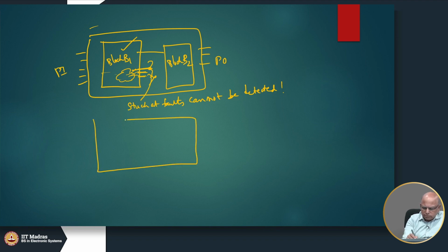Another thing could happen, right. I may have block B1, block B2, I connect all these guys, and there may be some inputs I do not need them. So, sometimes people tend to ground them or connect it to logic 1 and things like that. Okay. Because when I use B2, it is only these inputs that matter to me, the others are not important, but I can't leave them hanging.